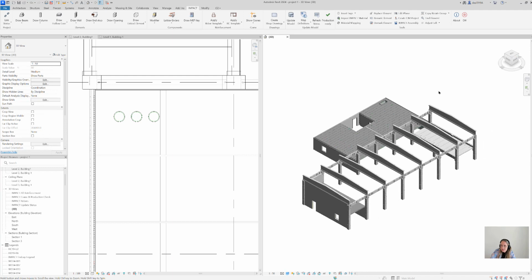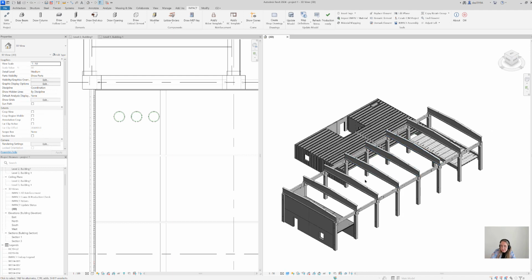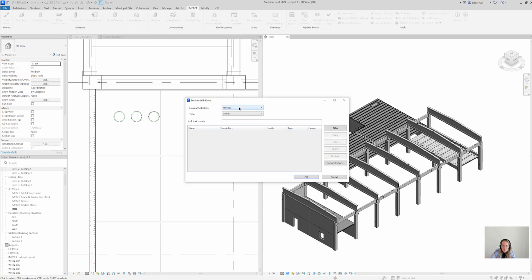Now, we need to jump further to the linked elements, and linked elements you're gonna find here in the Impact tab. What I want to demonstrate now is, first of all, if you need to draw a linked element, you need to have a family, of course, behind. The linked element can be everything, literally any family.